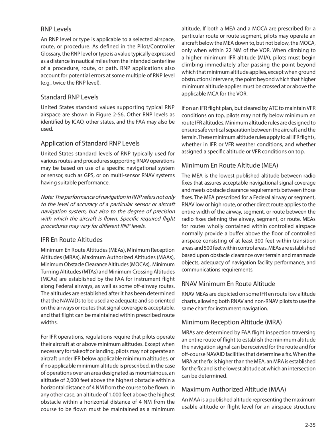For IFR operations, regulations require that pilots operate their aircraft at or above minimum altitudes. Except when necessary for takeoff or landing, pilots may not operate an aircraft under IFR below applicable minimum altitudes, or if no applicable minimum altitude is prescribed, in the case of operations over an area designated as mountainous, an altitude of 2,000 feet above the highest obstacle within a horizontal distance of 4 nautical miles from the course to be flown. In any other case, an altitude of 1,000 feet above the highest obstacle within a horizontal distance of 4 nautical miles from the course to be flown must be maintained as a minimum altitude.